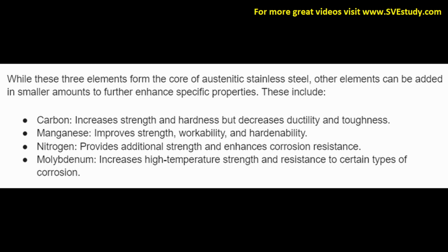Manganese improves strength, workability, and hardenability. Nitrogen provides additional strength and enhances corrosion resistance. Molybdenum increases high temperature strength and resistance to certain types of corrosion.